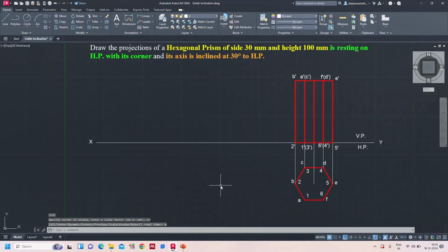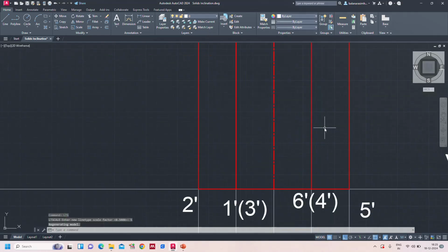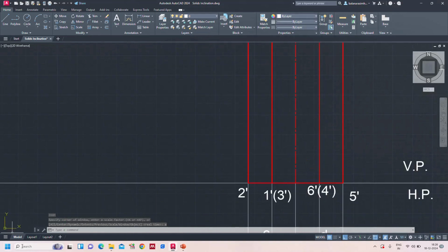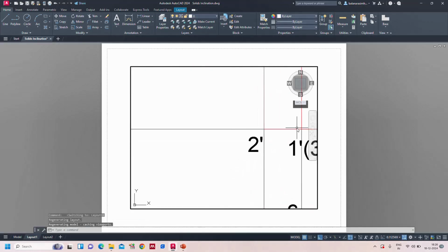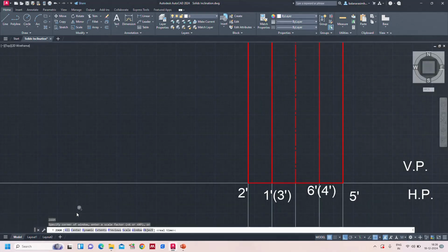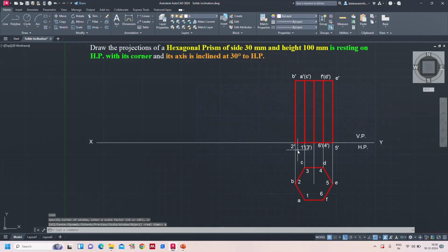Suppose if you want to see here line type scale, let us give 0.55, still not visible. Let me try with the line type scale 10. You can see the axis line here, but here it becomes a continuous line. So based on your visibility and adjustment, you can adjust.